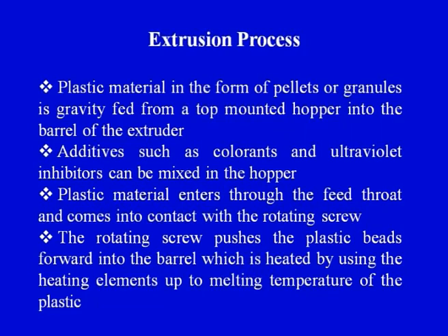Now the barrel is already heated with the help of heating elements up to the melting temperature of the plastic. So we are heating it to a particular level, and the level is higher than the melting temperature of the plastic. The plastic which we have entered in the form of a solid is in the form of a pellet. So the raw material that is entering is a solid pellet, and now these pellets, thousands of pellets, are melting because of the high temperature generated inside the barrel by the heating element. So the melting of the plastic pellets takes place.